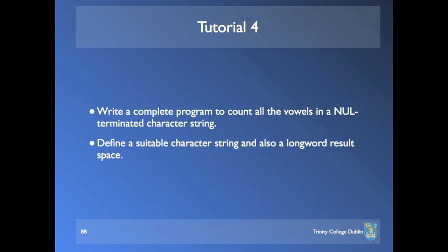Will moveq assume a long word? Yes, moveq always assumes a long word. It's a rather unusual instruction. It's in the slides. It always assumes a long word. It takes the 8-bit value that you specify and sign extends it up to 32 bits and puts it into the register. Say again?